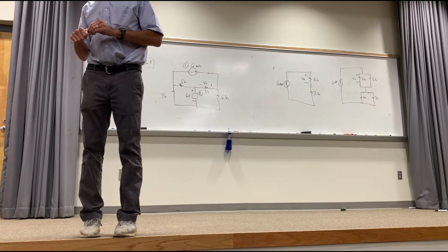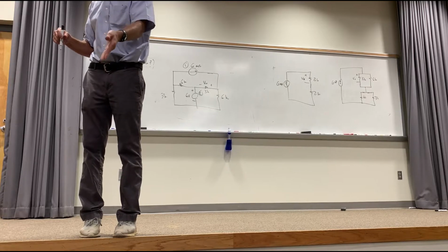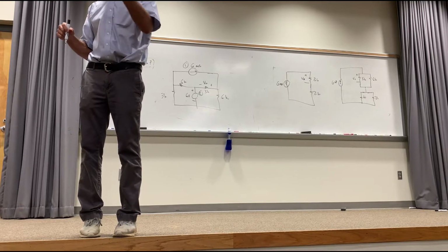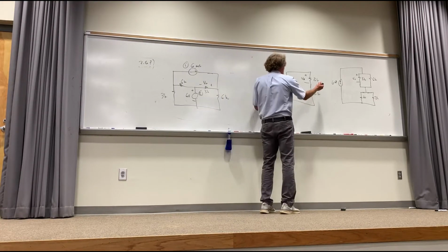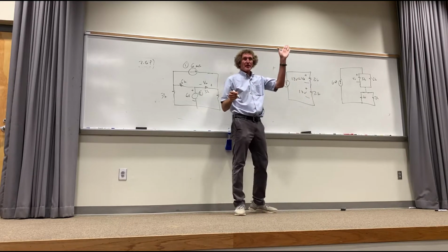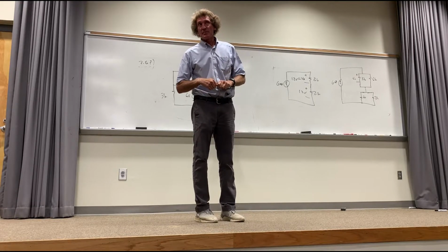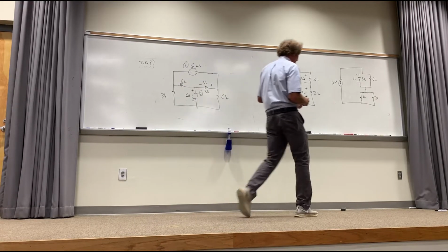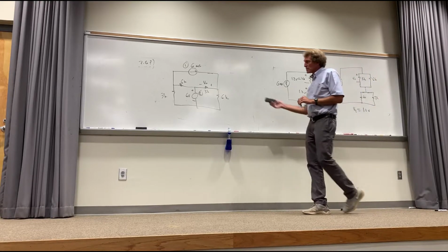Now what's that voltage going to be? By definition, V equals I times R. Do we know I? Yes, right? We know the current. Do we know R? Yes. What is the voltage? You multiply them. Can you all see that this voltage is 2K times 6 milliamps? Or it's what? 12 volts. So is that one, right? That's 12 volts. How many see this? It's not hard to see, but you got to do the redraw, right? Now, the next thing I do, so my first answer, or my V from the first source, call it V1, is simply going to be equal to 12 volts.